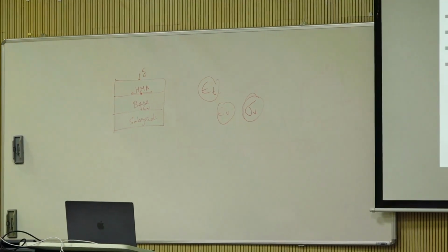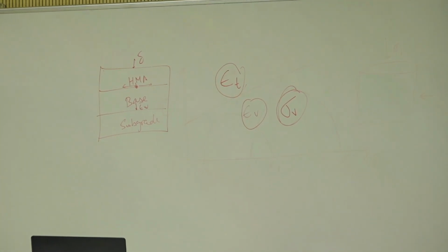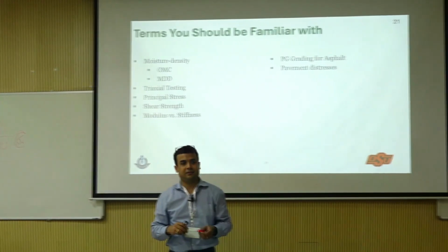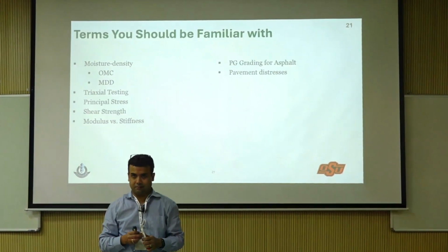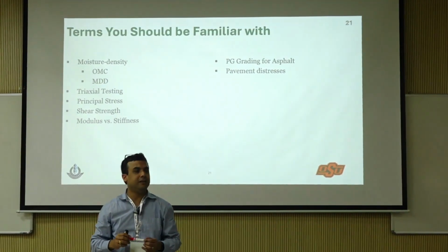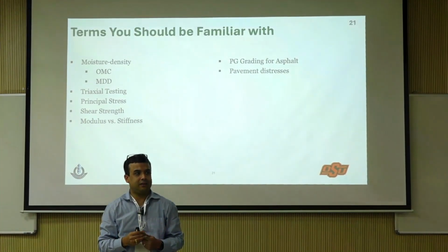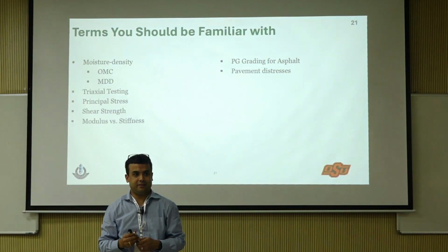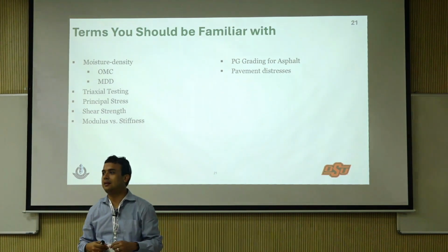Because we are getting into all this discussion, let me ask you another question here. What kind of a phenomenon is rutting? Vertical deformation, that's correct. Elastic or plastic? Plastic? Yes. What kind of analysis is any layered elastic analysis, like IIT PAVE, Ken layer, all of that?